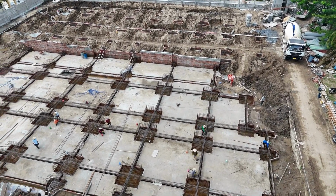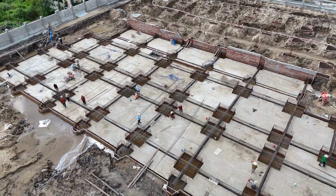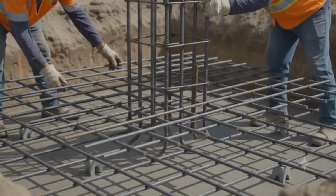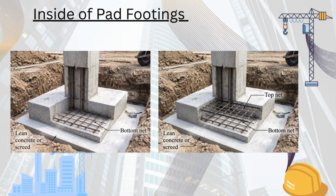Steel bars are arranged in both directions to form a reinforcement mesh. Cement concrete cover blocks are placed beneath the reinforcement to maintain the required concrete cover, which is generally between 40 and 75 millimeters, depending on the design and exposure conditions. This cover protects the reinforcement from moisture, corrosion, and fire. Depending on the structural design, the footing may contain a single layer or 2 layers of reinforcement. The size, spacing, and number of reinforcing bars are determined by the structural engineer based on design calculations.